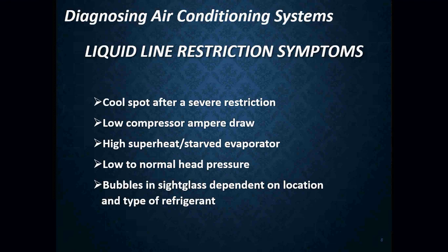Now, in terms of sight glasses, people will tell you, especially some mechanics that in many ways don't know what they're doing, that, oh, it's good to see bubbles going through a sight glass. No. Wrong. You do not want to see bubbles going through a sight glass. A sight glass is nothing more than a window to tell you whether or not you have a moisture-filled system or a dry system. That's all they're really for. They're not there to see whether or not the refrigerant is flowing. Okay? Which is a common misconception.